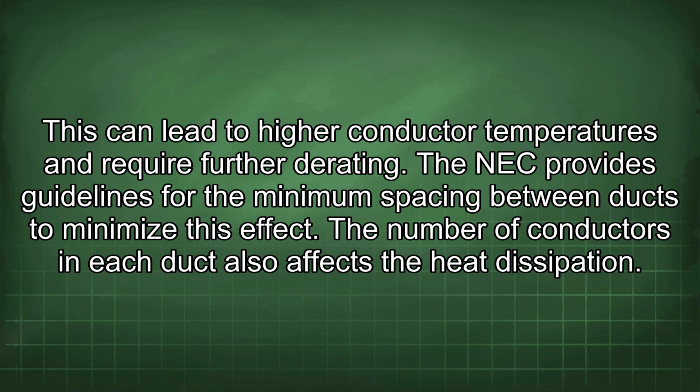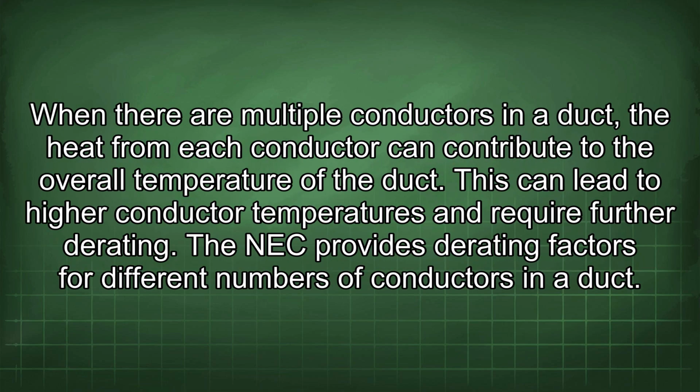The number of conductors in each duct also affects the heat dissipation. When there are multiple conductors in a duct, the heat from each conductor can contribute to the overall temperature of the duct. This can lead to higher conductor temperatures and require further derating. The NEC provides derating factors for different numbers of conductors in a duct.